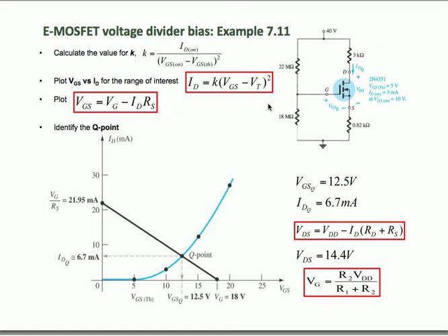So as you can see, the threshold voltage is 5 volts. So before the applied gate voltage reaches 5 volts, the transistor should not be giving any current, it should be 0. And only after the applied gate voltage exceeds the threshold voltage of 5 volts, the MOSFET starts to turn on and conduct drain current. So that's your second step.